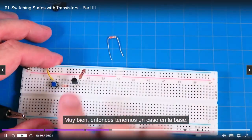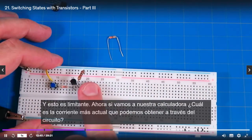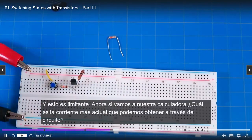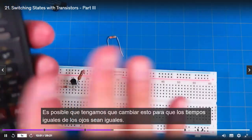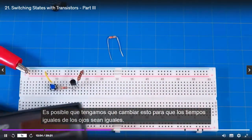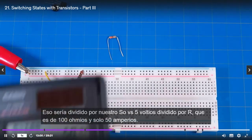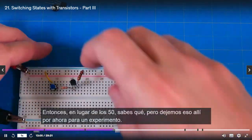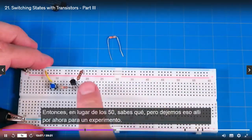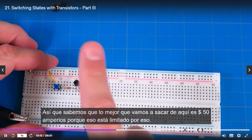Okay, so we've got 1K to the base. We've got 100 to the collector, and this is limiting. Now, if we go to our calculator, what's the most current we can get through this circuit? And we may have to change this. So V equals I times R, so current is V divided by R. V is 5 volts divided by R, which is 100 ohms, and that's only 50 milliamps. I'm going to tell you we're going to need more. But let's leave that in there for now for an experiment. So we know that the best we're going to get out of here is 50 milliamps, because that's limited by that.